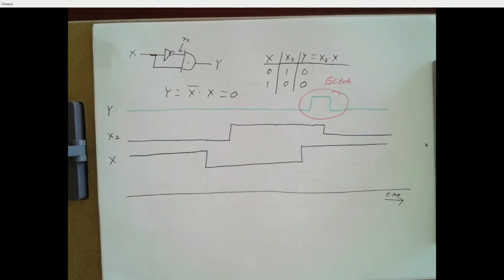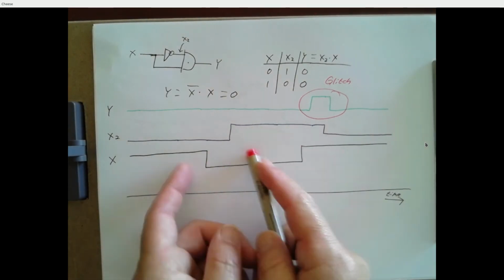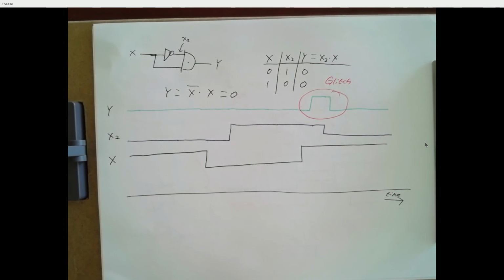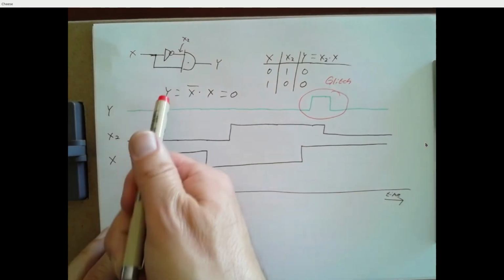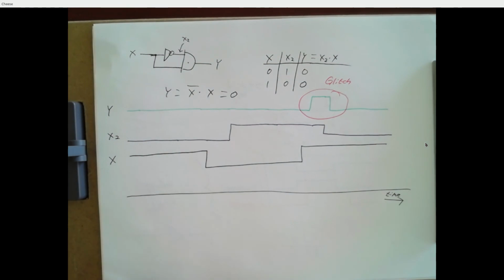And there you go. Okay, so this is the kind of thing that crashes satellites and stuff like that. And it can be notoriously tricky to avoid these things. And it's an artifact of these real-world delays in the behavior of circuits. And we think of circuits as idealized things. This is going to be x bar, this is x, the AND is always going to be a 0, right? So when we're designing circuits, a lot of times we're using very elaborate software tools, and one of the things these tools will do is they'll analyze our circuitry for things like this, or for the potential for glitches.